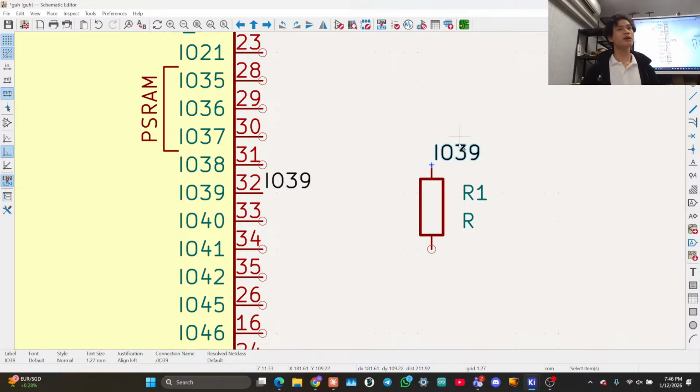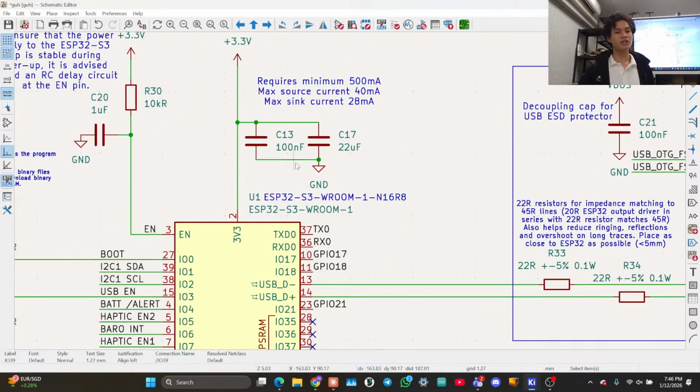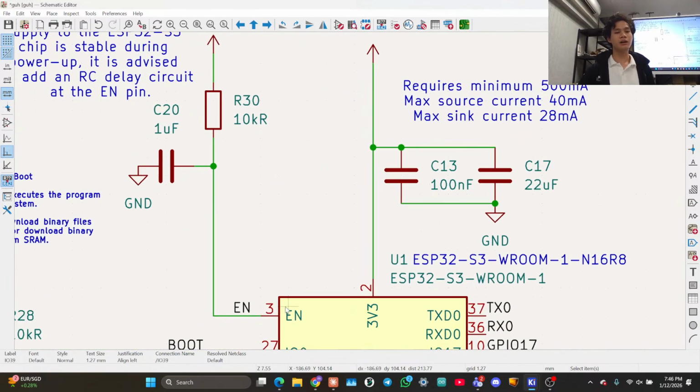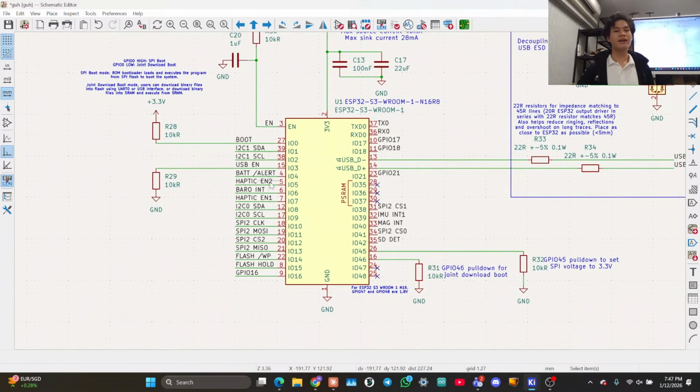Of course, sometimes wires are still cleaner. For example, you look at my application schematic, it's very clear how this is wired up. If I just did net labels for these, then I could place these anywhere, and people wouldn't even know that this capacitor existed. So having wires graphically draws the thing together, and that makes it readable sometimes. But if I had 1,000 wires coming out of this thing, then I would just die. So we use net labels for things which are very repetitive, or when there's a lot of them near to each other. Make sense?